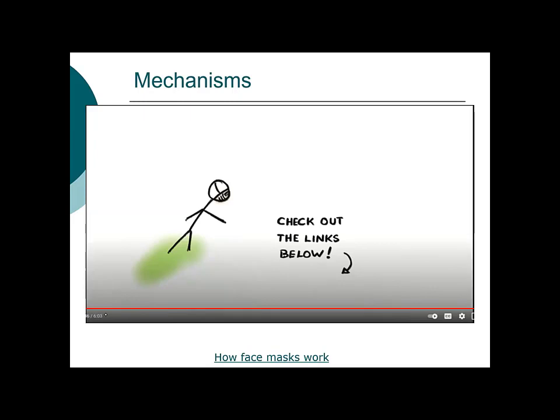The other thing that isn't mentioned in this video is how do the particles stay there? Because your filter material is only as good as its ability to retain those particles. If they're held there for a period of time, but then they dislodge and they can move through the filter, they're ineffective.